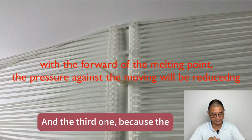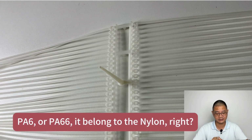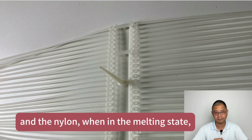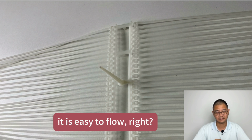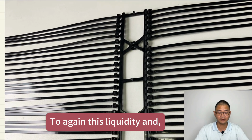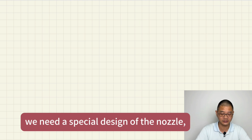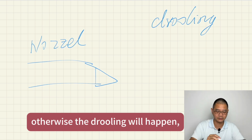And the third one, because nylon 6 or nylon 66 belongs to the nylon family, right? And nylon, in the melting stage, flows easily. It has very high fluidity. To counter this fluidity, we need a special design of the nozzle. Otherwise, drooling will happen.